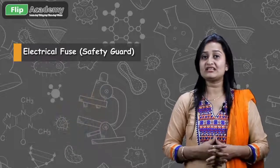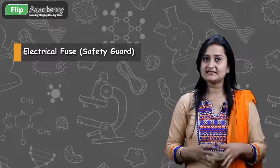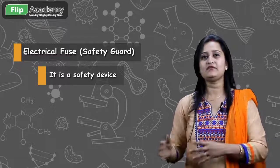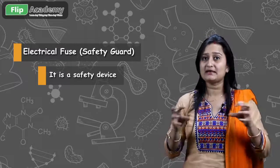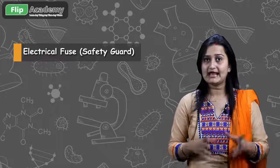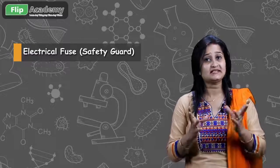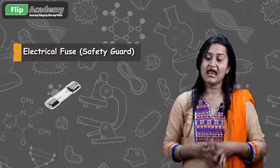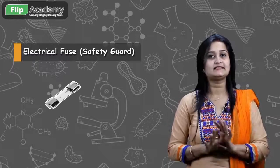So, in order to prevent this short circuit and the overloading, electrical fuses are provided. These electrical fuses, as I have already mentioned, are a safety device. So, whenever heavy current flows due to short circuit or overloading, then in that condition, your appliance will remain safe. How? Because the electrical fuse blows off. Whenever heavy current or overloading takes place in the live wire, then in that condition, excessive heat is produced, which results in the melting of the fuse wire. As the fuse wire melts, the remaining part of the circuit remains safe.